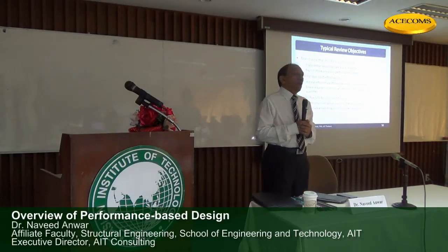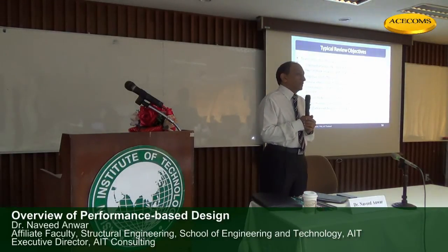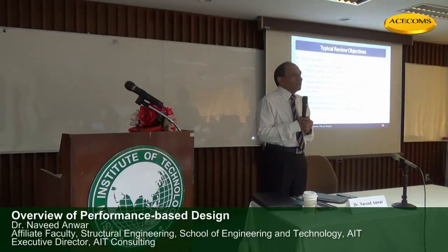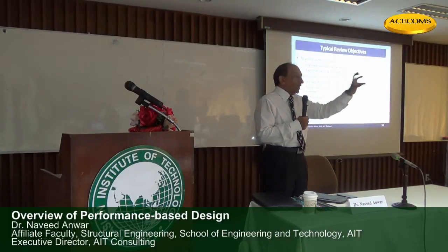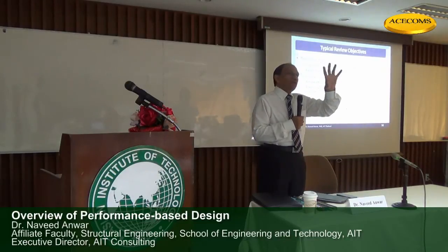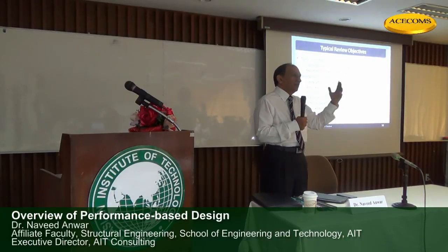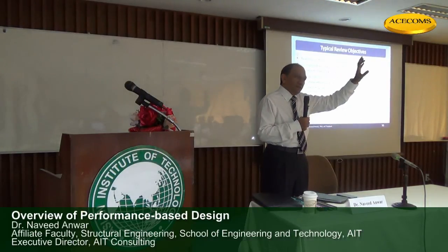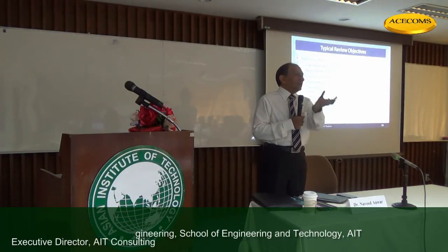Normally people think that if you do performance-based design, the structure will be more expensive. No, it doesn't have to be, because we will know where to take out and where to add the reinforcement of materials and so on, because we will know which elements are critical, which are not. So non-critical, reduce the reinforcement. Critical, increase the reinforcement.